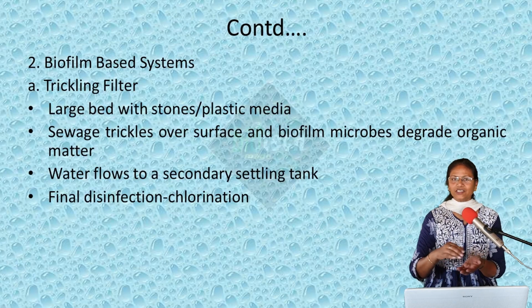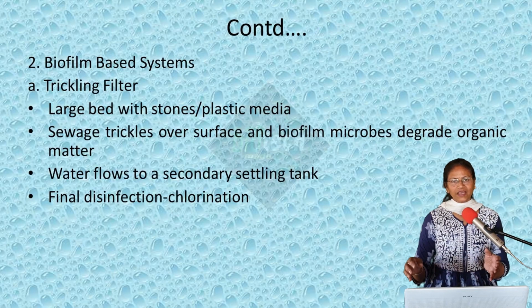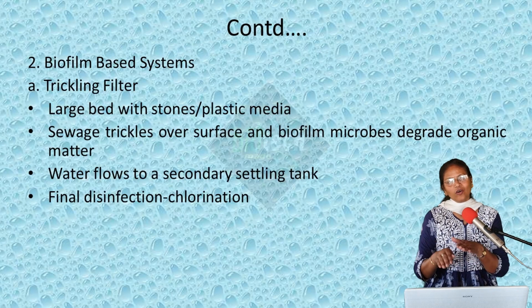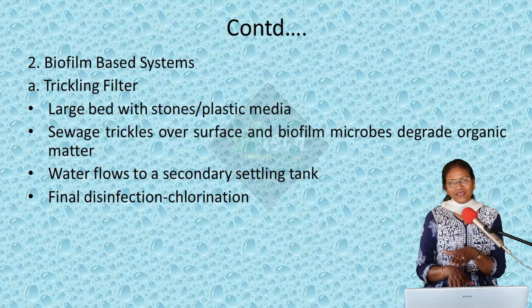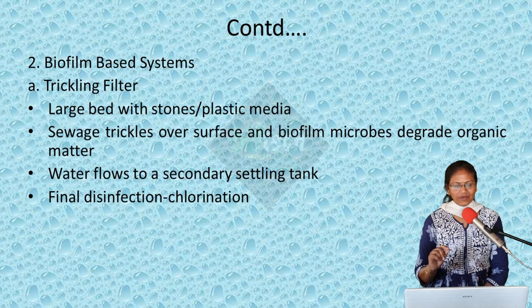So biofilm is actually the film which is formed by the microorganisms because they stick to each other, they produce a mucilaginous substance around them, and also these microorganisms stick to the surface. So on all these carriers, the stones or plastic media, whatever is there, they grow and form a film like structure which is known as biofilm.